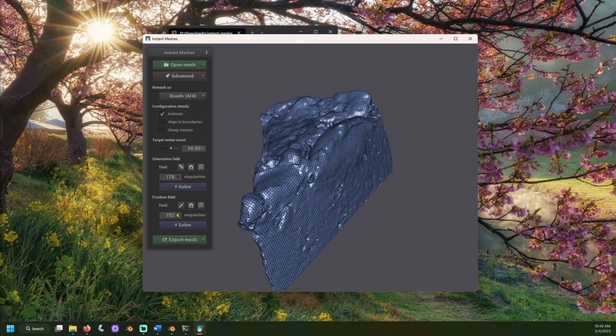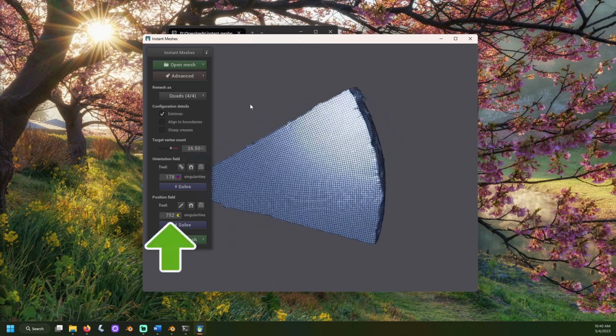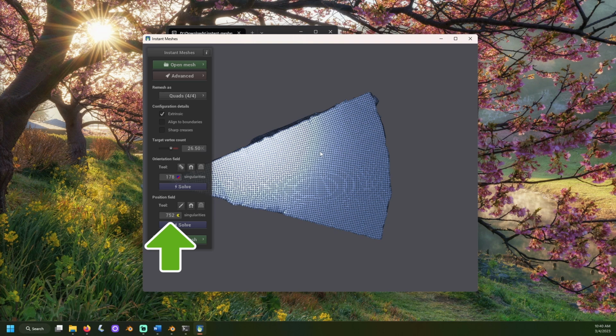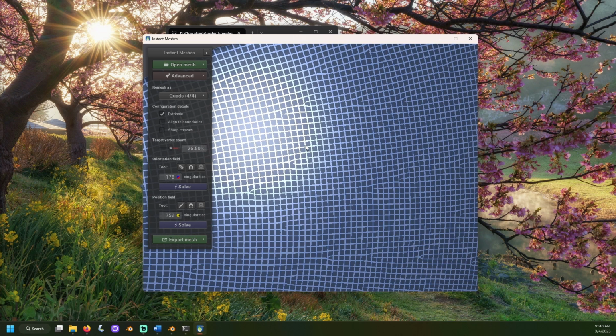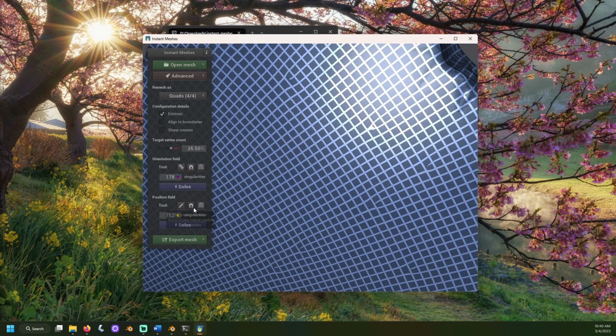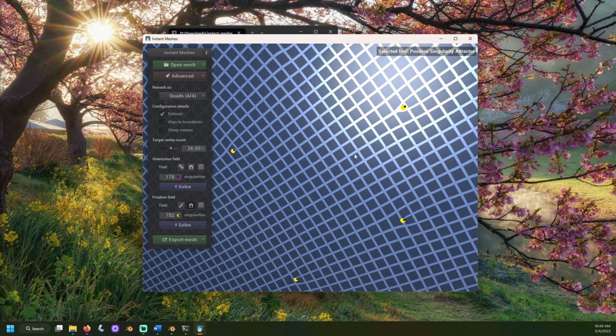Before exporting, take a quick look at the value next to Singularities. It can be difficult to get perfect structures of all squares. If you look around, you'll see V shapes, like forks in the road. These are called kites. Each singularity represents a kite somewhere on your mesh. To move a kite, select the magnet. Now you can see the little Pac-Man symbols all around. You can click them and drag a line from them. If the kite believes it can move to that location, it will.